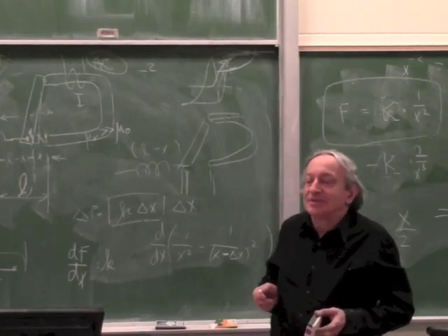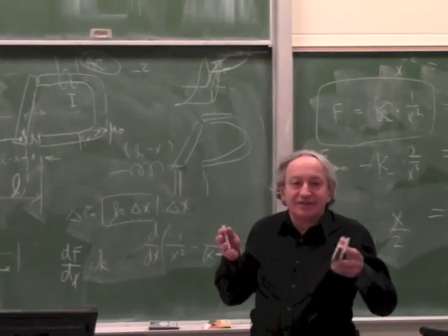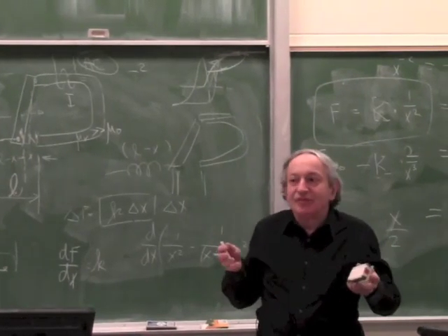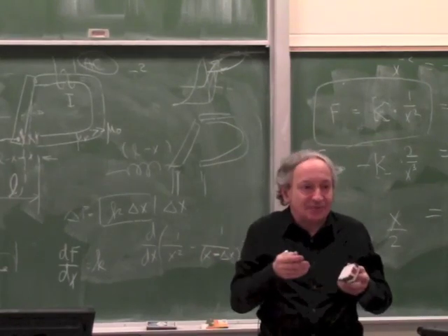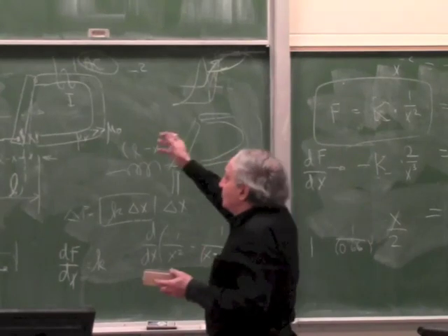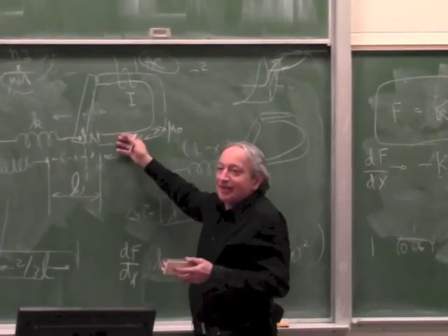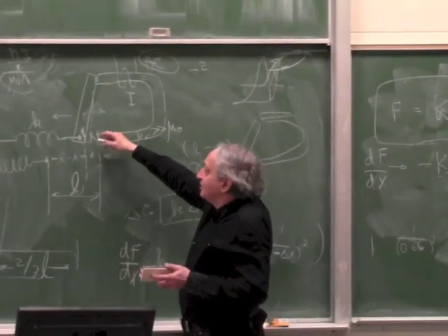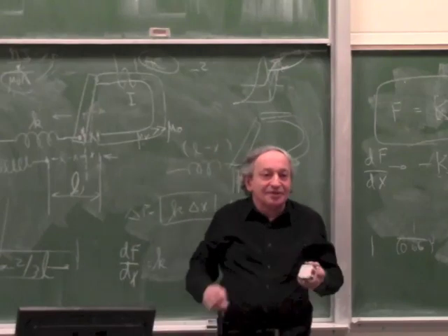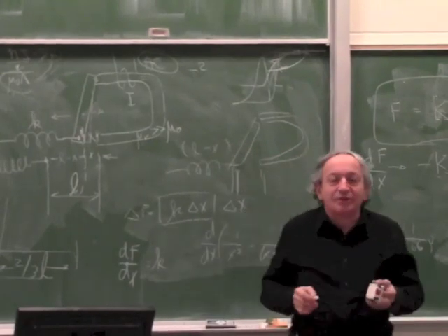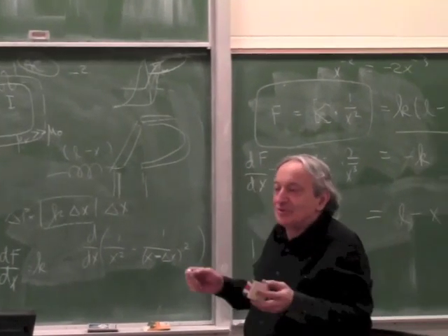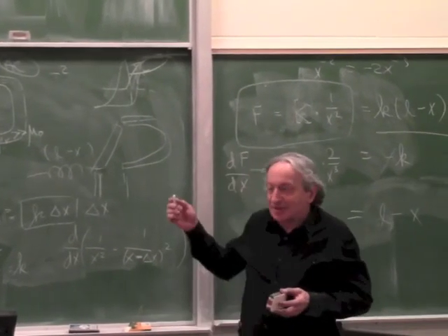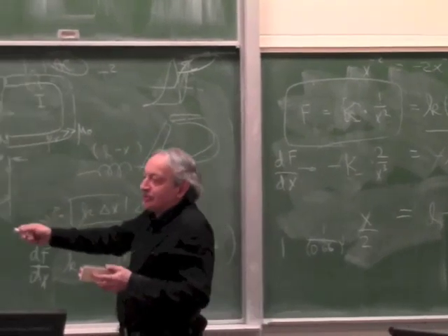Another example where the actuator has to be vented, like open to the air, moving iron will not collect metallic debris or magnetic debris, because as soon as you stop the current, it stops being a magnet, so all the little particles it collected will fall out. So there are some circumstances where you have to use moving iron. But apart from that, don't use it for a servo, because as you can see, it's a problematic actuator to control.